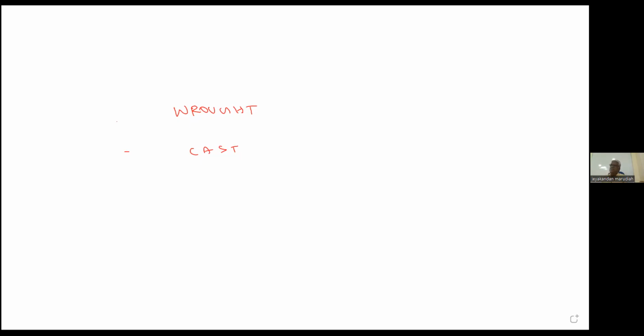Now, when you receive the material, it will come with material test certificates. Again, there are two types of material test certificates. Cast analysis, sometimes called ladle analysis. Another one is called product analysis. Cast analysis means during the ingot stage, they take a sample and test it. Product analysis means the final product like a pipe or plate, they will check. Which one is important for the inspector, cast analysis or product analysis? Product analysis, final product.